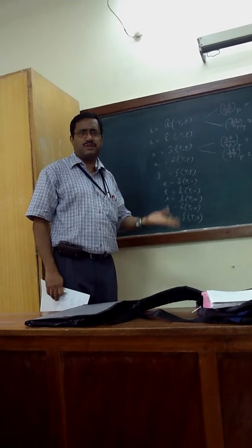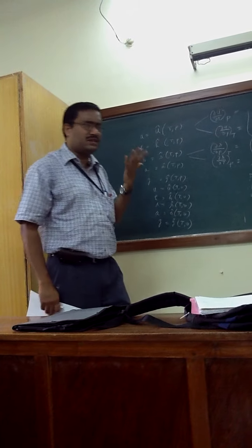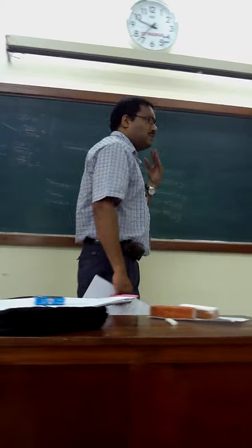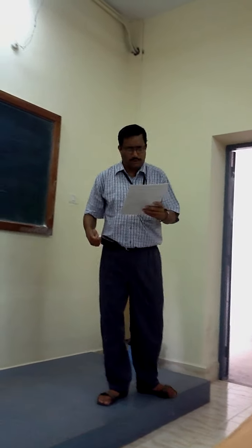Either we go for temperature and pressure, or temperature and volume, as independent properties. PV you can do, but it is a bit cumbersome, because temperature is very easy to measure. Either pressure or volume you can measure. That's it. We can have the complete prediction of the system.